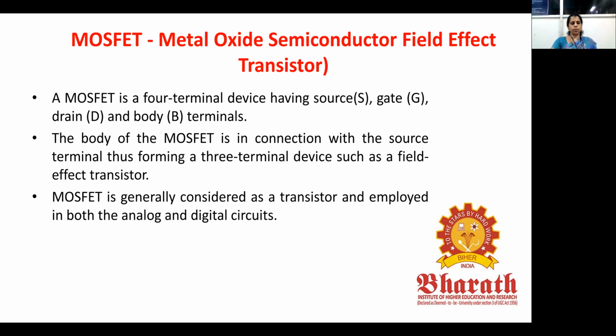So coming to MOSFET. MOSFET and IGBT are voltage control devices. Previously we saw SCR, which is a current control device, and MOSFET is a voltage control device. It comes under the FET family. We call it metal oxide semiconductor field effect transistor. It has 3 terminals: gate, source and drain.